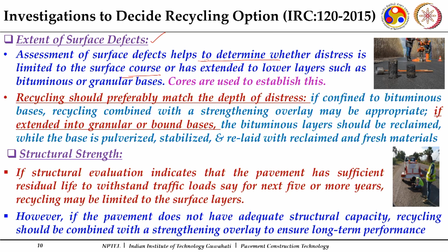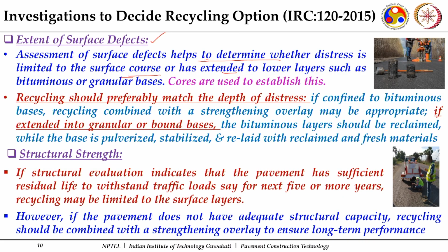Otherwise, it may not serve the purpose, and that distress may reoccur also. So it is important to understand whether the distress is limited to the surface course only, in which case a surface recycling can be good enough, or has extended to lower layers such as bituminous, or if the problem exists with the granular courses, or even up to the subgrade level.